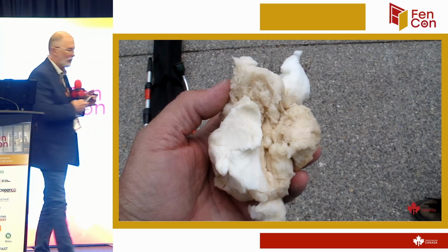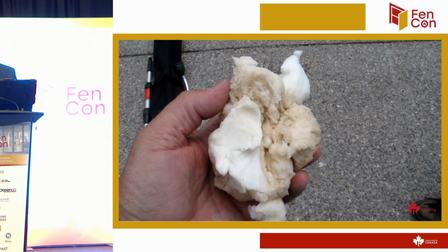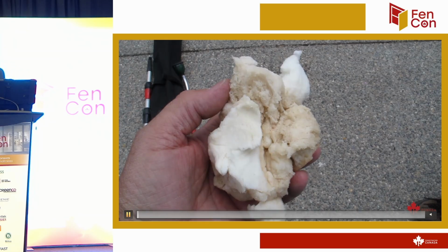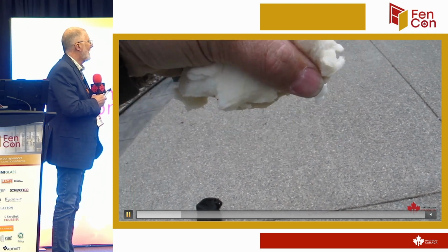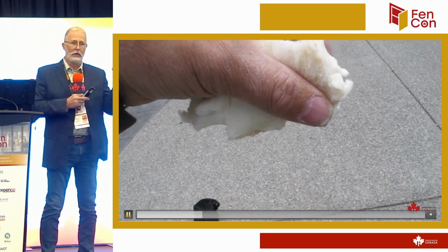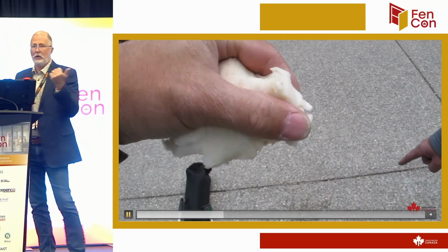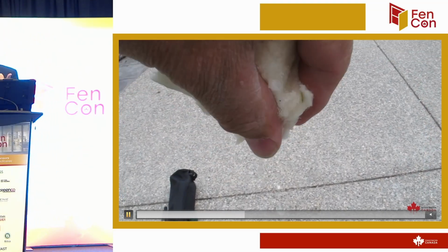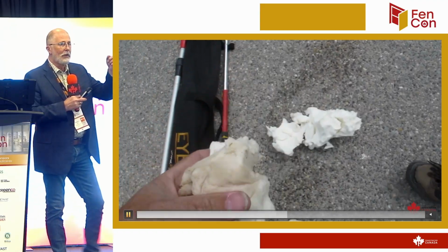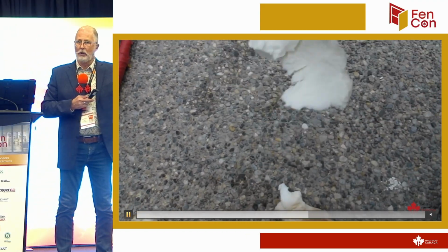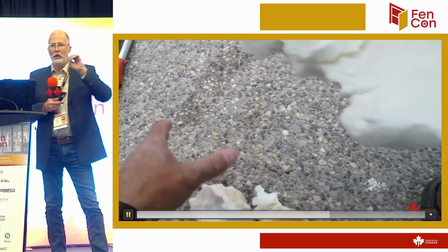All right. So let's go back and talk about spray foam. Is spray foam water resistant? When you look at most spray foams, they can be water resistant depending on the type. Closed cell medium density spray foams are water resistant. A lot of the newer window foams form a skin on them so that they become water resistant. They don't soak up water. They're hydrophobic.